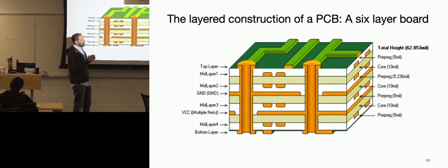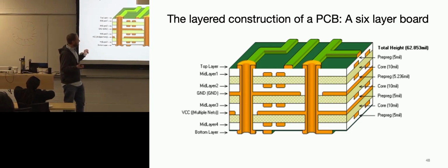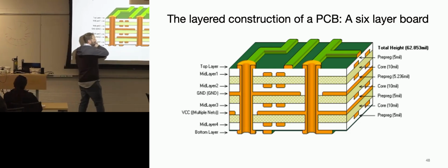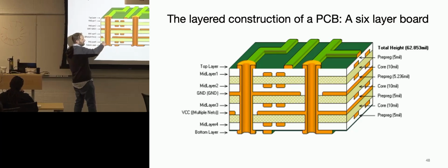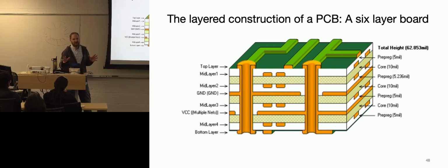Power planes are fine if you've got a 14 or 20 layer PCB. You don't really need it. You can just have wires themselves going through the power plane or that other inner layer, and then you can use the other space for routing signals as well. That's my suggestion. Any questions so far? Randomly just talking about PCBs by myself.